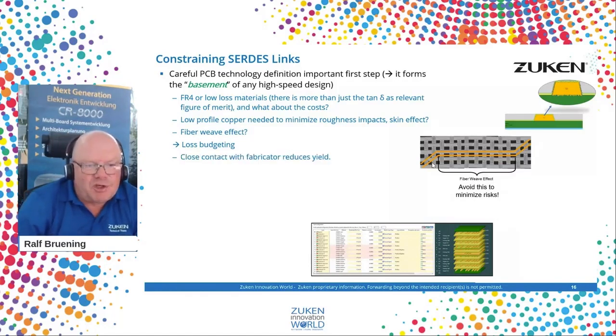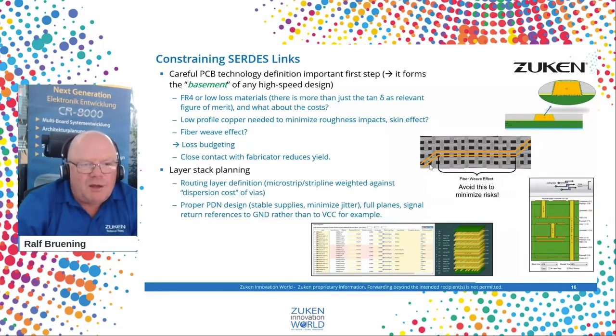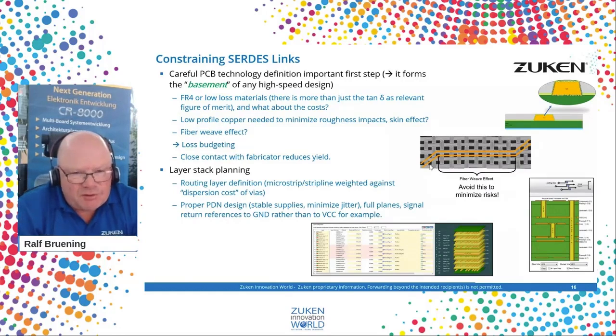So layer stack definition. That's more or less defining the basement of your design, like defining the basement of your house during the construction. Close contacts to manufacturers is pretty important for a successful SerDes design. Layer stack planning, routing layer definition, and again, loss budgeting.